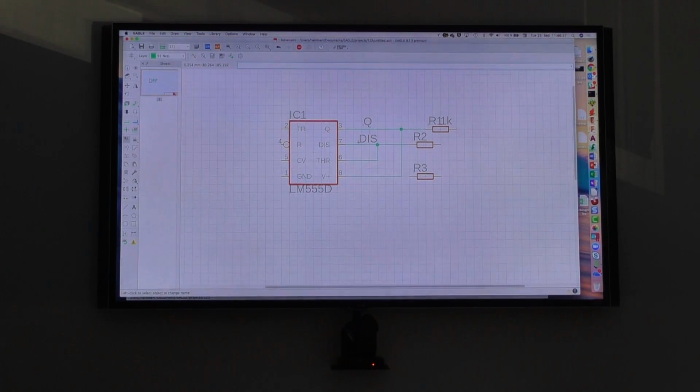Besides that, in my opinion the texts are too big, so it makes sense to really name the schematic nets, because if somebody has to read this, it's better understandable. Think of some service people who have to go to the customer who says, hey, my schematic does something wrong, what can I do? It makes sense to have the names of it. It's much easier for them to understand what happened. So that's basically a very simple schematic.